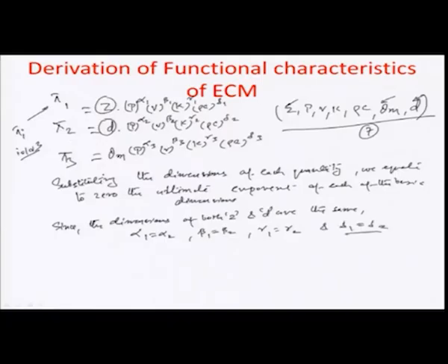As you can see here, if all the basic dimensions are equated to 0, this particular pi 1 would have a 0 dimension, and so the remaining alpha 1, beta 1, gamma 1 and delta 1 would combine to be equal to length inverse for making this dimensionless. Because this also has the same dimension length L, alpha 2, beta 2, gamma 2 and delta 2 would combine together to again have the length inverse dimension. They are equal to each other and can be equated to each other. So, that is why alpha 1 equals alpha 2 and so on and so forth.